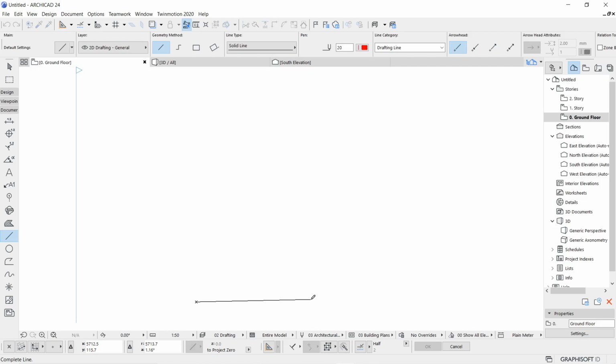Okay. So now we are going to complete that 4500 millimeter segment, which is horizontal. Coordinate-wise, for its X value, again I'm going to press X from the keyboard. I'm going to type 4500, no enter key. Be careful, no enter key. Then I'm going to press Y and the value for Y will be 0, and I'm going to use the enter key. Now my segment is drawn.